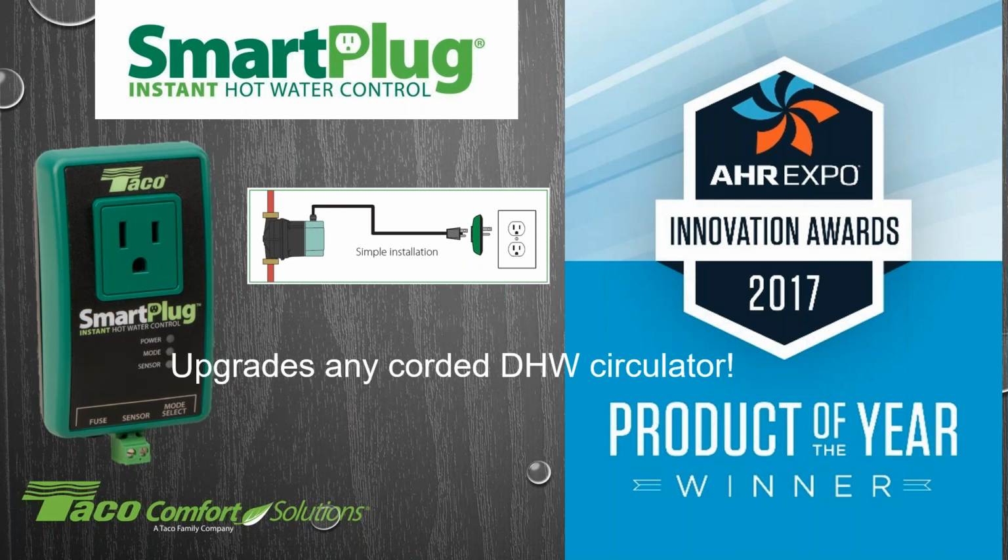For example, your timer, not a bad way to go. However, it does have a couple of faults. One, we have power outages. You have a power outage, the clock itself is stuck where the power went out. When the power comes back on again, you end up with the timer being set for the wrong time of day for when it turns on. So that becomes a challenge. And two, twice a year, depending on where you are, we end up with daylight savings, and that's going to throw off your schedule.